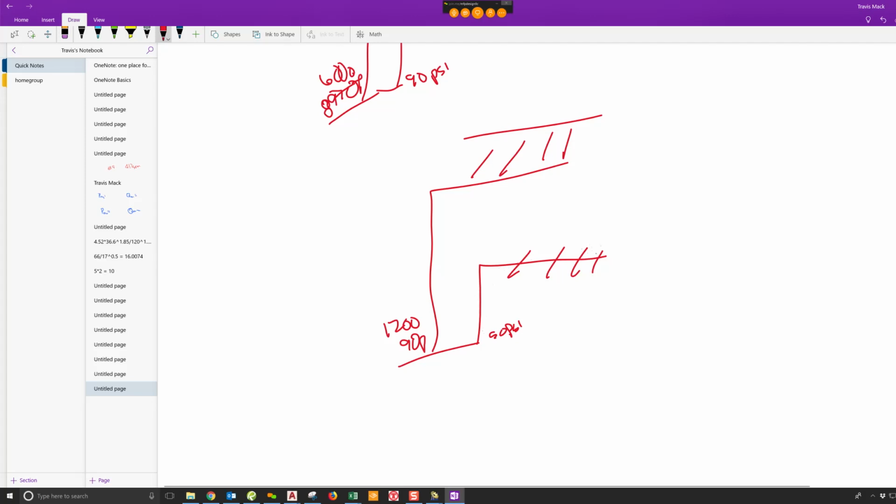So maybe instead of these being 1.25-inch lines, I shrink them down to 1 inch. Instead of this being a 3-inch rack main, I shrink it down to 2.5-inch. Because I want to get this pressure here as close as I can to this pressure here. So again, bigger pipe doesn't always win. If you're doing a residential attic, like some of these dry system attics, they're just a nightmare trying to calc. Sometimes smaller pipe is better because if you can look at what you're getting at your various points.